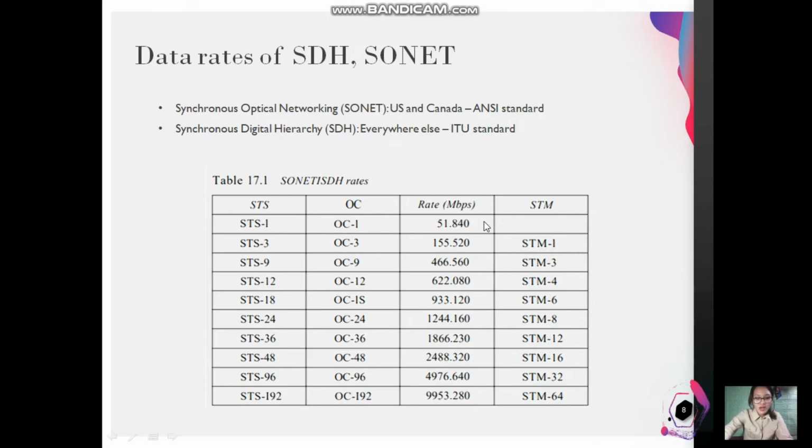First, the lowest level in this hierarchy has a data rate of 51.840 Mbps, which is greater than that of the DS3 service, which I mentioned a while ago, which was 44.736 Mbps. In fact, the STS-1 is designed to accommodate data rates equivalent to those of the DS3 rates. The difference in capacity is provided to handle the overhead needs of the optical system.